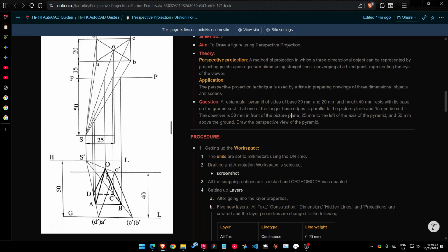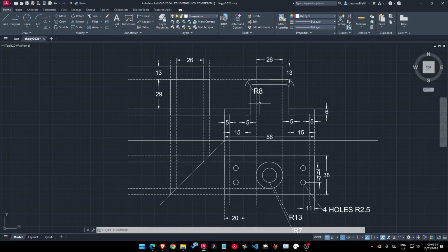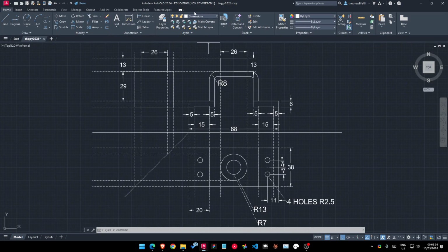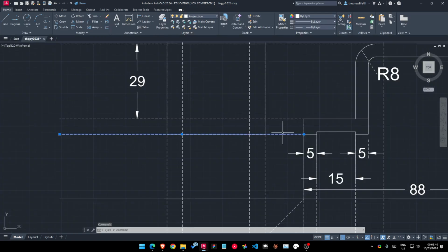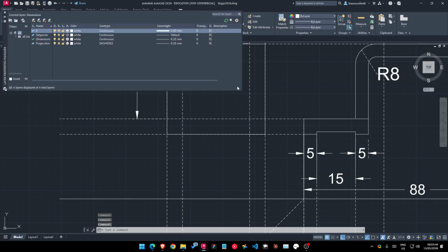And the ones that you're not supposed to see, they're going to be hidden, so you put them in another layer, which is, wait, let me show one thing. This is where you access the layers, by the way, and this is how I get these lines which are dashed. See, there are different layers here. We can go into layer properties and you can just make new layers, or just do Alt N to get a new layer.